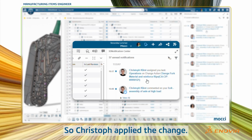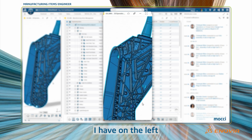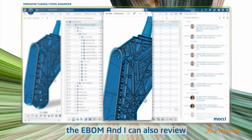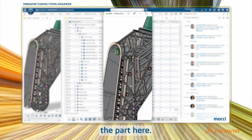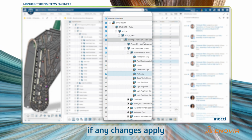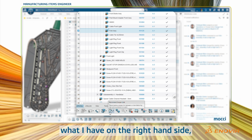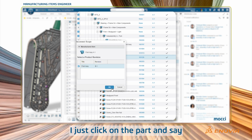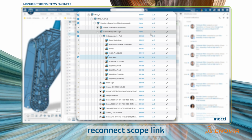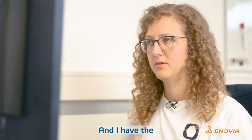So Christoph applied the change, and I get the notification in the 3D experience platform. I have on the left-hand side the EBOM, and I can also review the part here. I can check the new structure and see if any changes apply to the assembly or to manufacturing. And in the MBOM, on the right-hand side, I just click on the part and say reconnect scope link. There's the new revision B, and it will replace with the new revision. And I have the actual and fresh MBOM here.